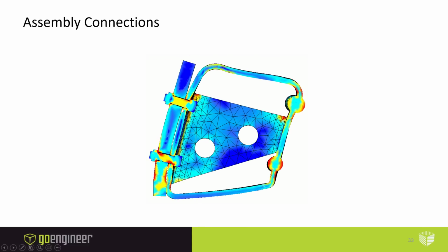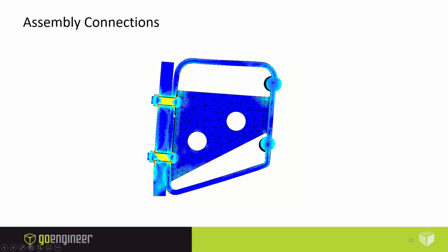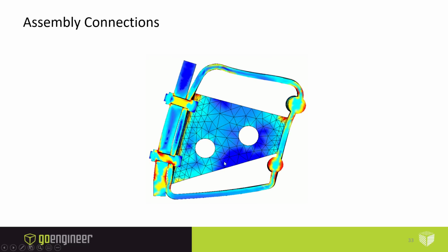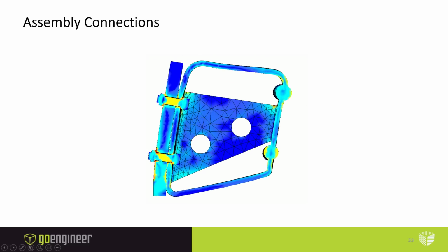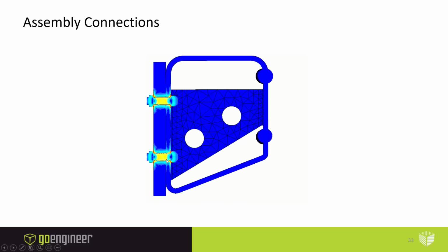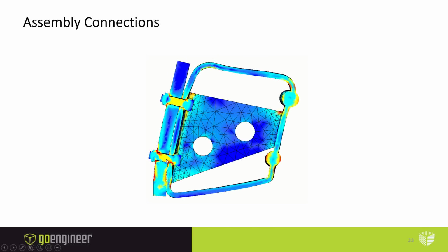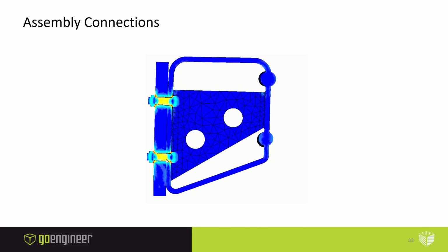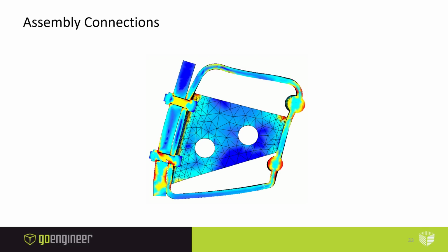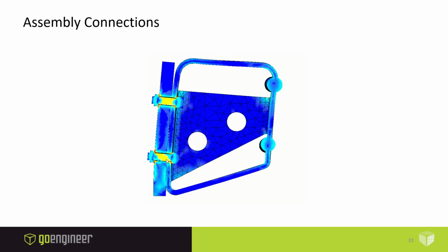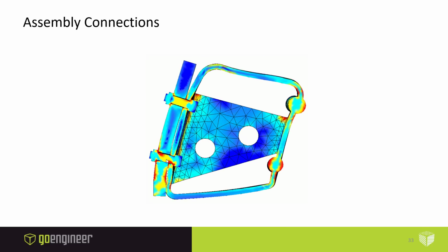Okay, but I just want to give you a sense that if I really exaggerate the deformation, you can see why a lot of those stresses are going to the bottom bolt. You can kind of see the way these things bend, and you end up seeing more shear in this bottom bolt. This is more direct modeling, not what we just covered. I'm just showing you a higher level of detail where you could potentially take it, but it's generally not recommended to go this high.